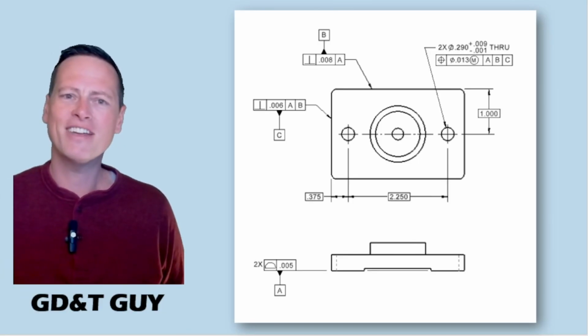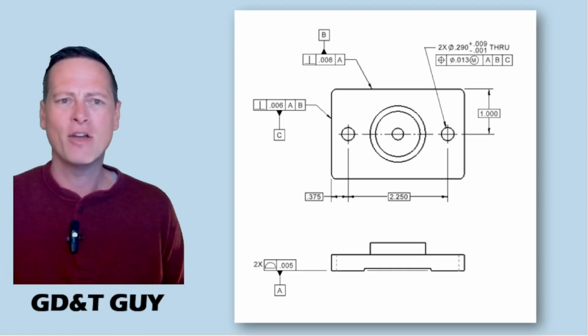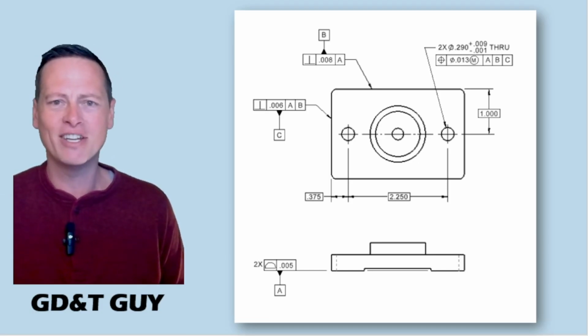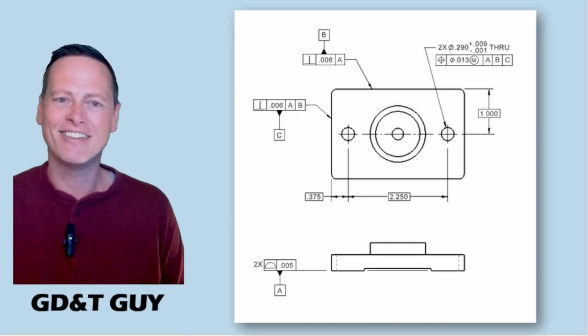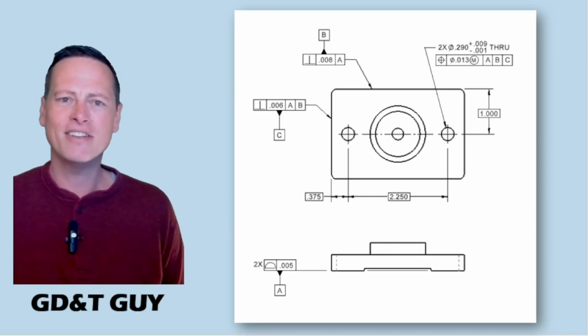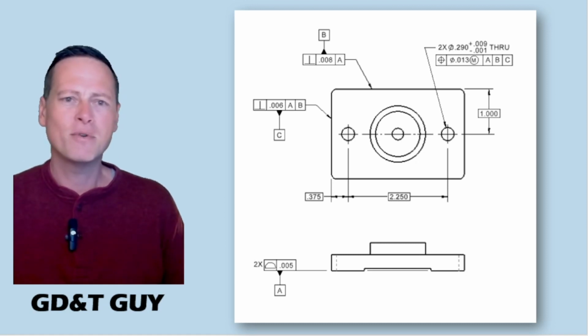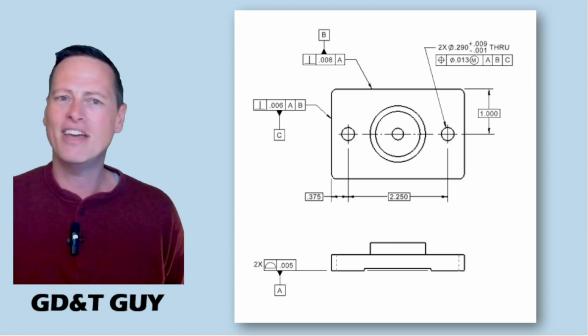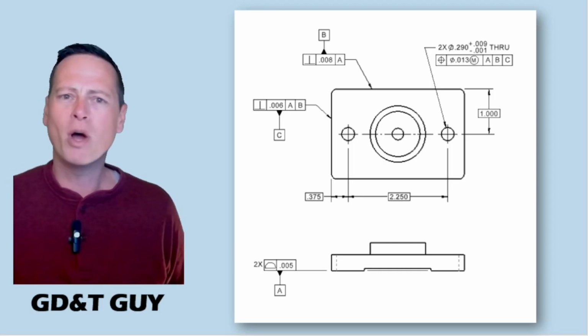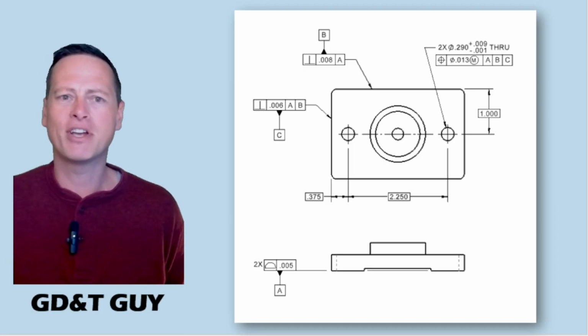Now, everybody who's taken some GD&T training or who has a nice chart on their cubicle wall or their toolbox, they'll know that in the GD&T system, every part must be constrained in 6 degrees of freedom, right? And usually the way it is presented is something like what you see in figure 4-2 of the standard, or something like this, where the idea is, okay, there's one large surface across the bottom. Actually, this one has a relief in it, but the coplanar surfaces have a relatively big footprint.